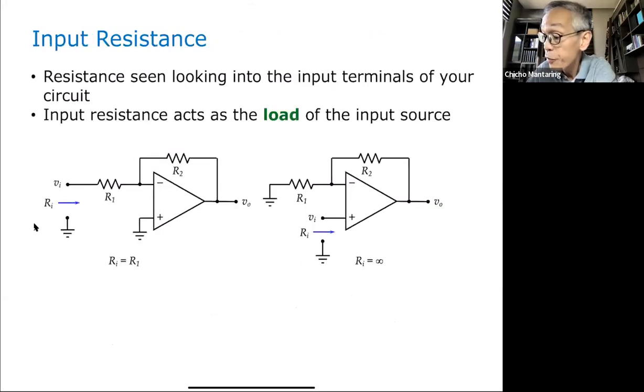If you have an inverting amplifier, what does the input look like to what it is connected to? Because this is a virtual short, this Rs of I, the input, is just going to look like R1. Because this is virtually shorted to this. In other words, if I put a test voltage here, you recall how you get equivalent resistance?